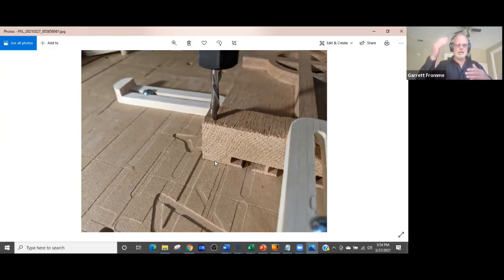So in the Z, it has a stroke. Let's just say it's got a 3-inch stroke. And once it passes that 3 inches, it comes to a hard stop. It physically can't go any further. Your controller knows this. And so when you start to run your program and it sees something in that G-code that says I'm going to 3.5, based on all the things that are set up.